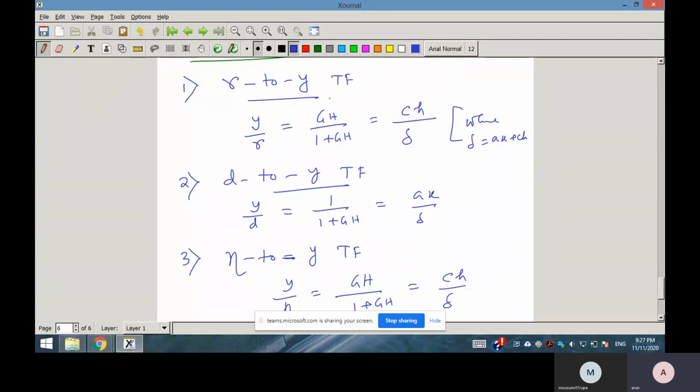Similarly, in pole placement, you place delta, but you do not know where the controller poles will get placed. Once delta is placed, the controller pole and zero polynomials automatically get placed. If the roots of KS are close to the imaginary axis, there will be amplification of disturbance to output, and disturbance attenuation will be poor.